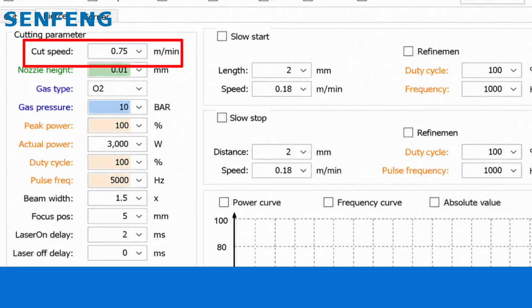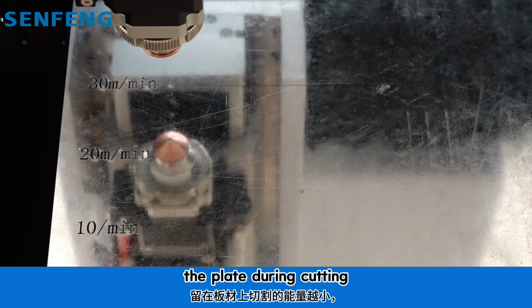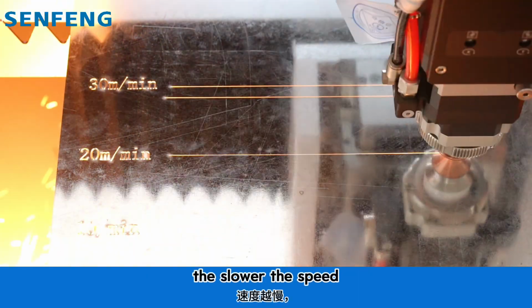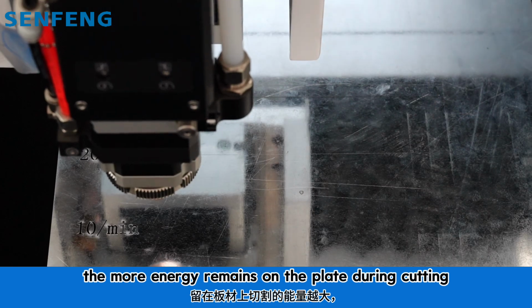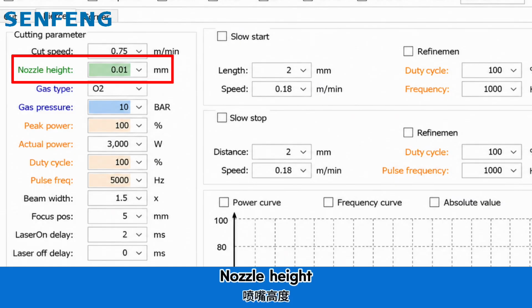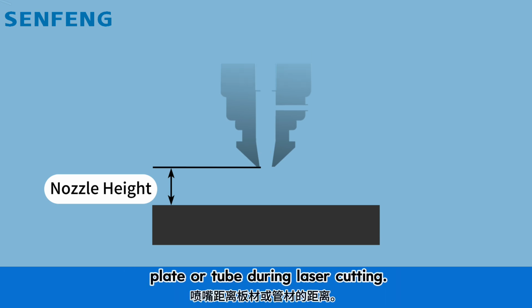Cut speed. The speed at which the laser cuts. The higher the speed, the less energy remains on the plate during cutting, resulting in a shallower cutting depth. The slower the speed, the more energy remains on the plate during cutting, which may lead to overburning. Nozzle height. The distance between the nozzle and the plate or tube during laser cutting.